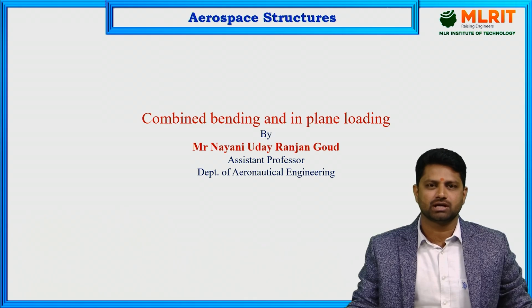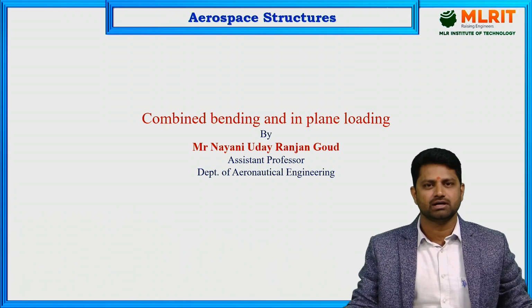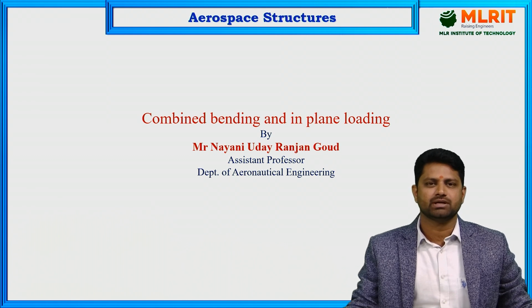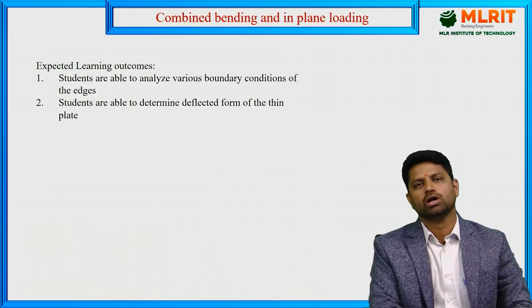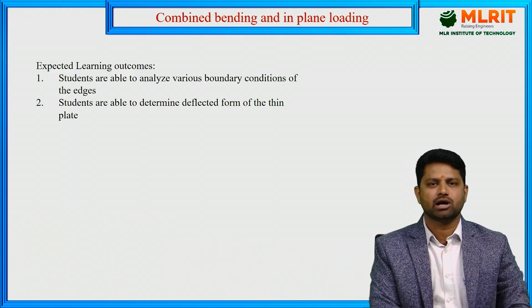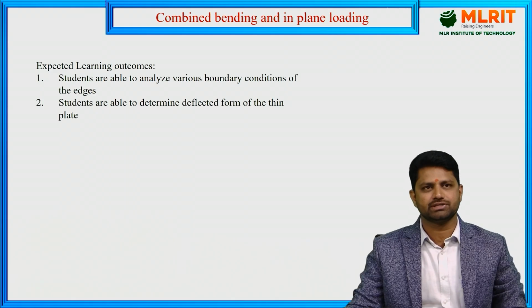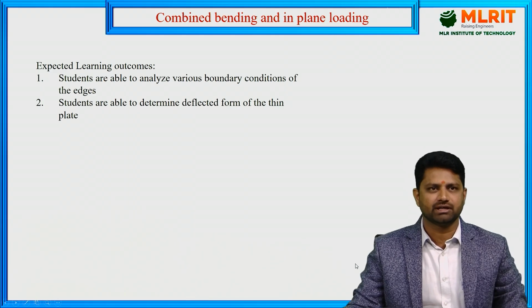In-plane loads are nothing but the additional loads which are encountered on the aircraft surface, apart from the bending, twisting and transverse loads. If these in-plane loads are of less intensity, they may not affect the bending of the plate, but if the intensity is more, then they are going to affect the bending of the plate. So in this module, we are going to see such a case: the combined bending and in-plane loading. The learning outcomes are: students are able to analyze various boundary conditions of the edges, and students are able to determine the deflected form of the thin plate.